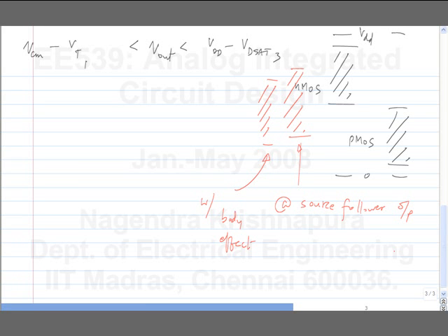The VGS of the source follower increases as the output voltage increases. So at the upper side, it will have a much larger drop. So the swing reduces even more. The bottom line is the swing that you can get by driving a source follower from a differential pair is rather small. PMOS instead of NMOS. So that's what will happen then.